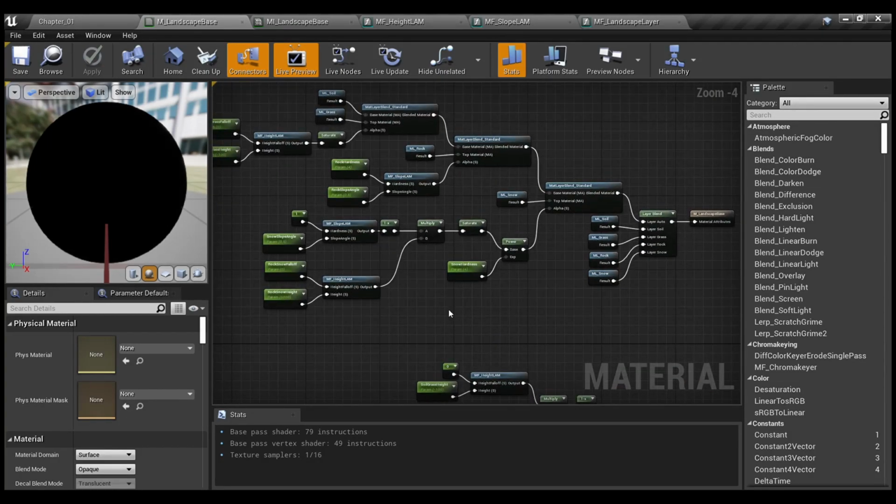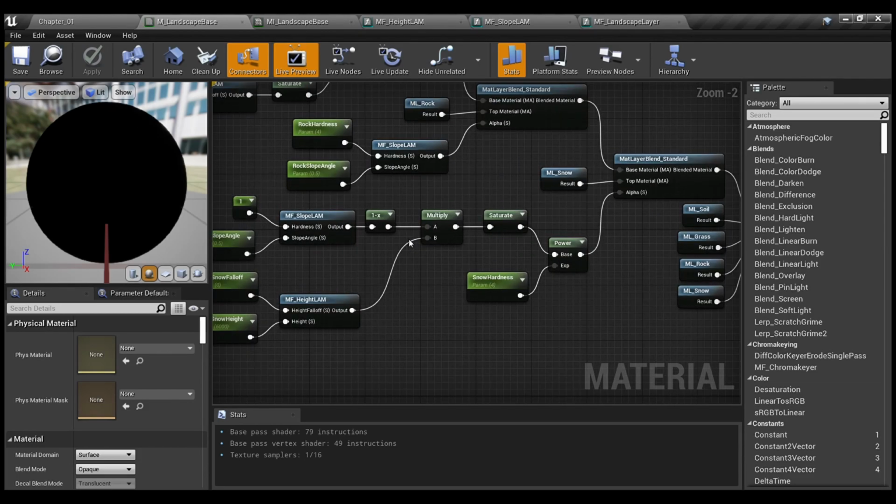Also, I'd like to note that for this moment I haven't found a pretty good solution for using physical materials inside auto material. It doesn't handle right, but when the time comes, I guess maybe Epic will support it in a better way, or I'll find a solution somehow. So if you want to have physical materials supported with the auto material, you should probably do the following: apply auto material, then with some sort of brush just overpaint the physical material on the proper areas.